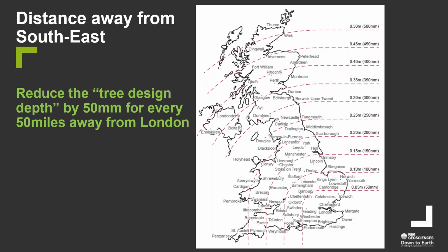Taking the point about distance away from the southeast, to some extent this probably has a little bit to do with anticipated climate change. We're aware of the geology. The geology itself will make the shrinkability of the soil be high shrinkage design, and the tree charts take that into account in the way in which they put the depths forward on the chapter 4.2 design charts.